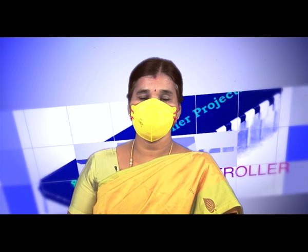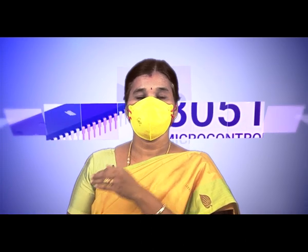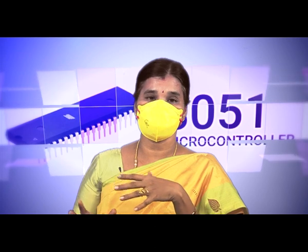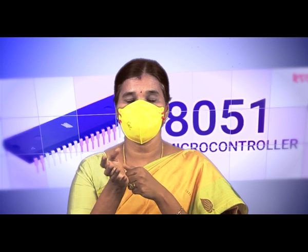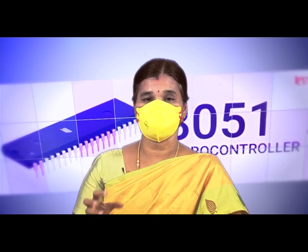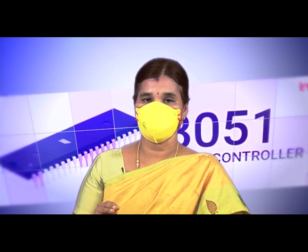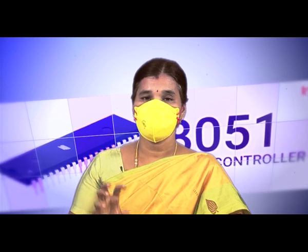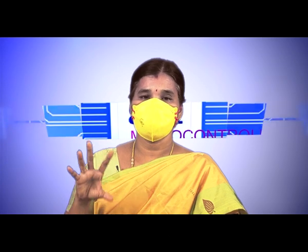In today's session we have discussed the 4 ports. The 4 ports each have 8 signals, so totally 32 signals, and each circuit is repeated, so 32 different circuits are used. How to activate the signals as either input or output depends on the corresponding port's functions. In case of port 0, it is used as input, output, address and data lines, right. In case of port 1, it is simple IO mode, either 8 input lines or 8 output lines. In case of port 2, it is used as 8 input lines, 8 output lines and 8 address lines.